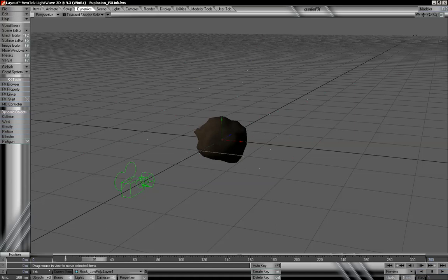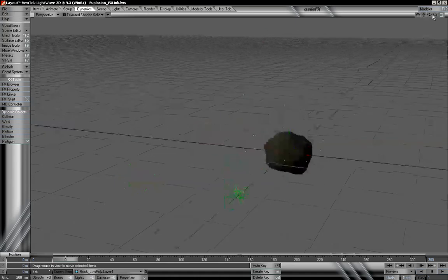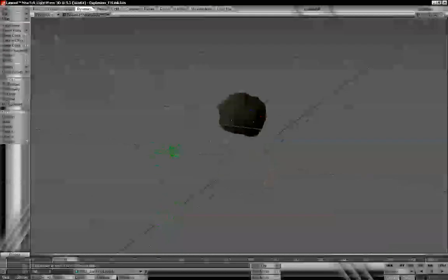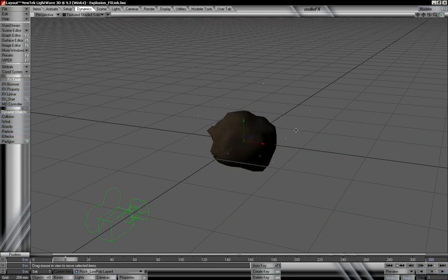But what I want to do now is create motion that's going to follow along with one of these particles, so we can get an idea of how to set this object up. And then once we have this one object set up with all the dynamics added, and even using the effects linker with a lot of it, then we can copy and save those motions, not baking them, but just the settings themselves, and apply them to all the other objects.